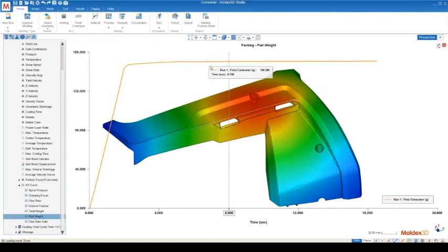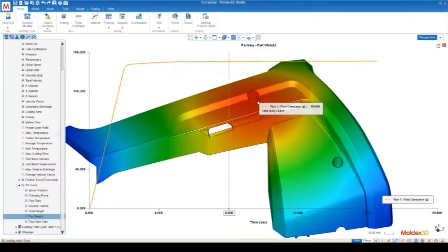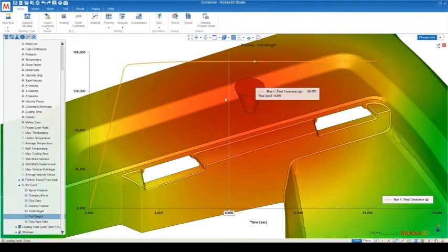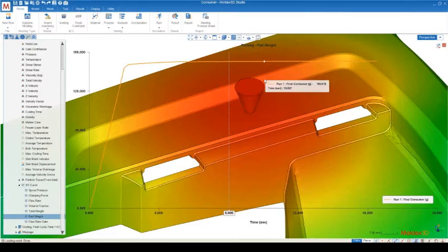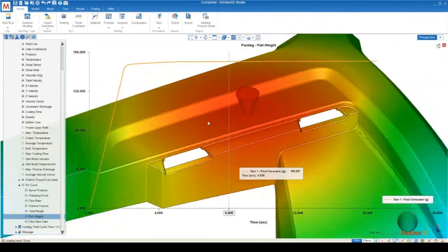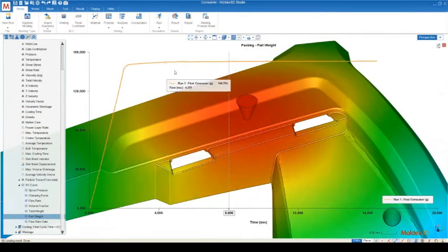And the reason for that is there's a feedback loop between the pressure that we're exerting onto the material in the part and the pressure that the material in the part is exerting back onto the material that we're applying pressure to originally. So there can actually be a negative flow rate. You'll actually see a negative part weight change.